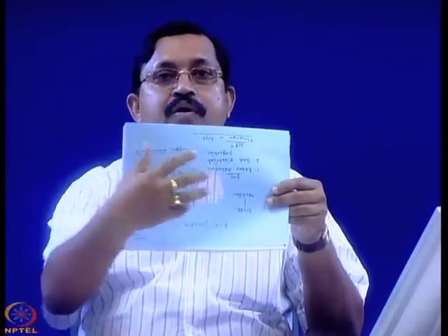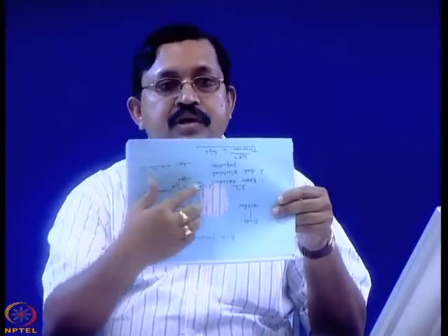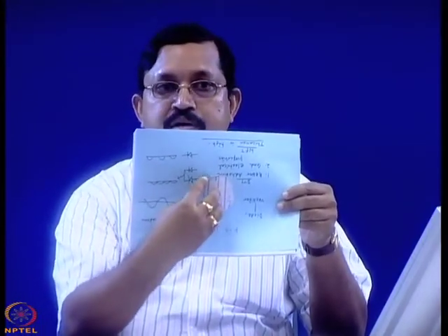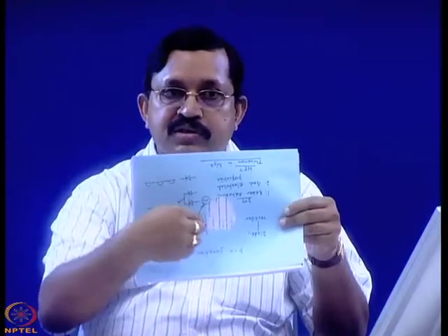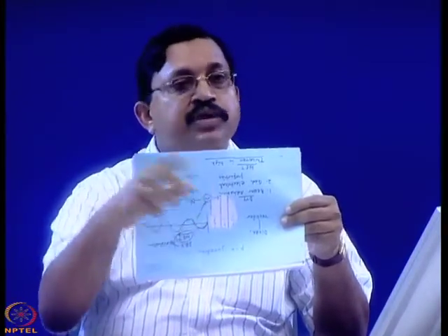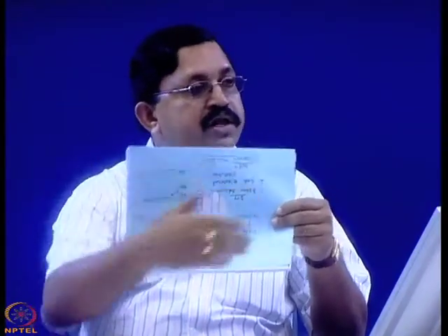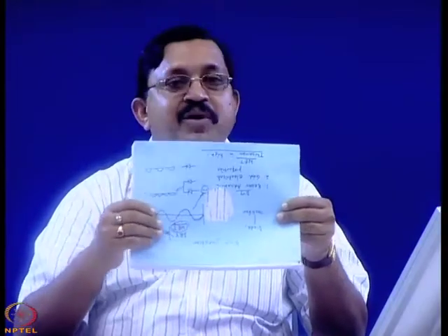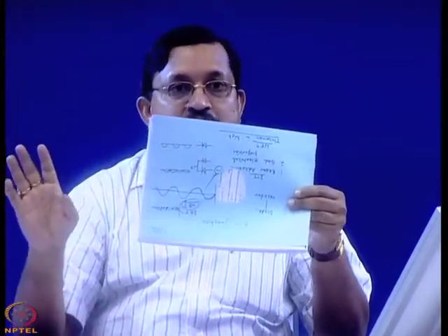Now, when ultraviolet light falls on it, only in the window region the ultraviolet light will come in direct contact with the photoresist. That portion will be hardened, that portion will be polymerized, and in the rest of the portions the ultraviolet light will be blocked by the glass plate. So, it will not be hardened, right.